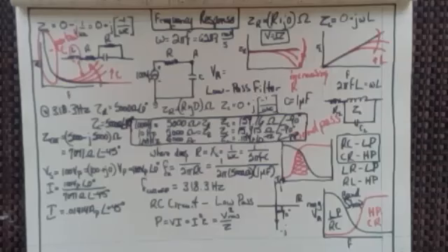And you're trying to find out what is that capacitance factor in that circuit. And you can do it this way. You can just roll it in on the oscilloscope to get that 45 degrees, and that is your resonance frequency, right? As you change the frequency to get the phase shift between the current and the voltage at 45 degrees, pow, that tells you what your capacitive loading or your resistive loading, if you know the other one, is in your circuit. All right, so that's our current, and that is peak things, and then you can find out what the voltage is at A.